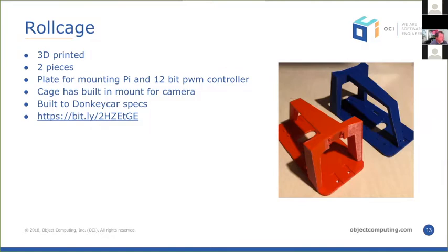Now the roll cage, we got these plans. They're based on the DonkeyCar, but these roll cages are 3D printed into 2 pieces. So there's a top part here, and then there's this bottom part that holds the board. And we basically take the chassis body top off of the RC car, and we put this on instead. So you can see the holes here in the main board are mounted on the strut towers of the suspension of the car, and then it just basically cotter pins that in so it stays in place.